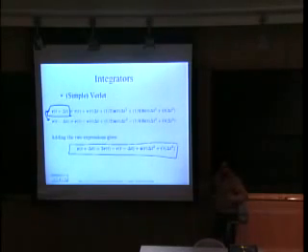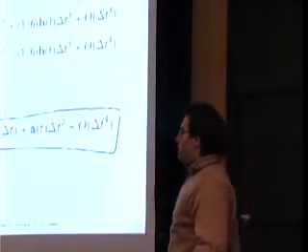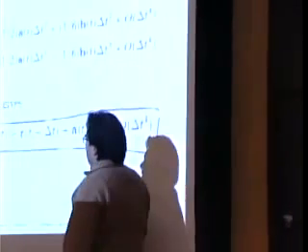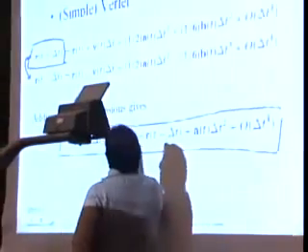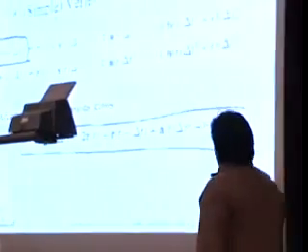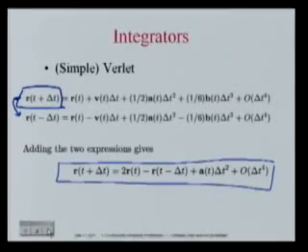That means that the smaller we make the delta t, the smaller we make the time step, the more accurate our integration is. And so this is, if you want, the most critical parameter in your molecular dynamics simulation. You need to make sure that the steps that you take are small enough, considering what is really the variation of your force as a function of time.